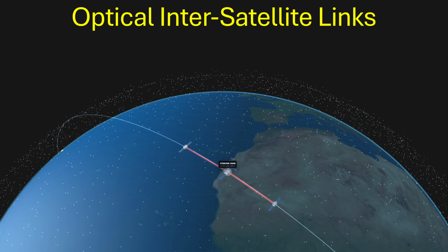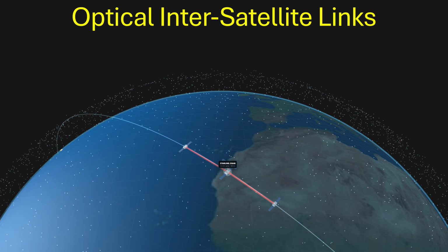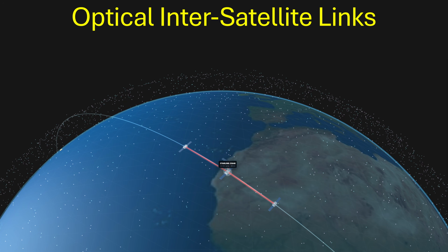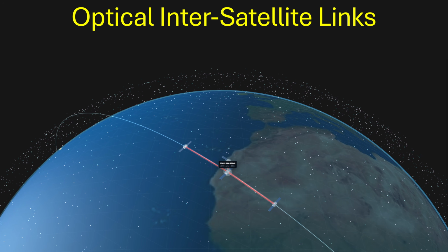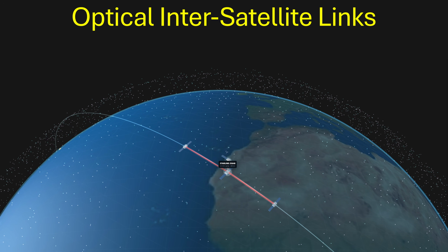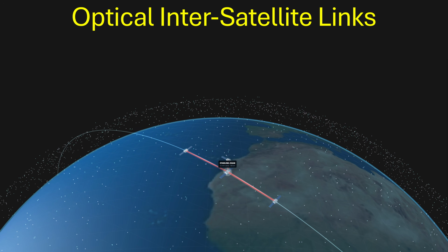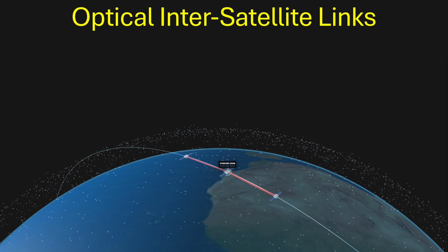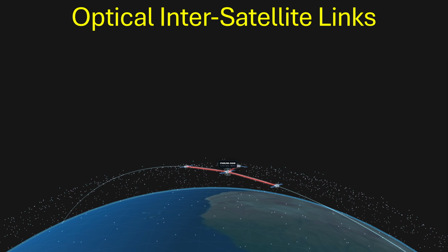Now let's move on to space laser links. Optical inter-satellite links are somewhat similar to fiber-based optical communication systems. The key differences are that there is no attenuation or chromatic aberration from glass fiber, no amplifiers in free space, and the beam will spread since it is not confined within a single mode fiber. The beam also needs to be precisely pointed between distant moving satellites.